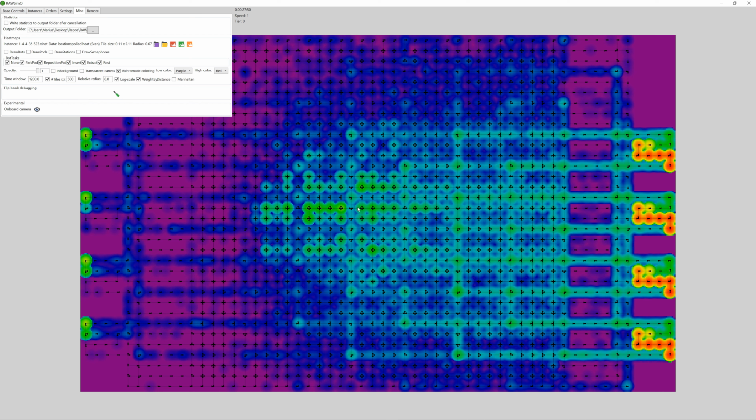For example, we can see in here that we have somewhat more bubbles. This is because typically a robot in the default setting, like we've chosen, if it's dwelling, if it's not doing anything, chooses an unoccupied storage location where it idles. And this is typically one in the middle. This rule can be modified, of course, but this is what resulted in robots hanging around here and spending a lot more time in here.